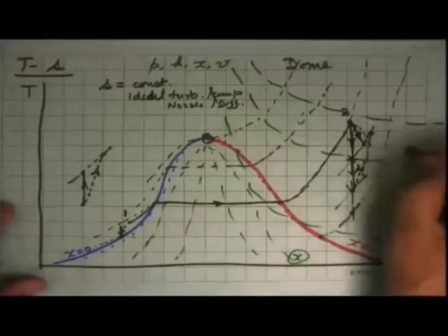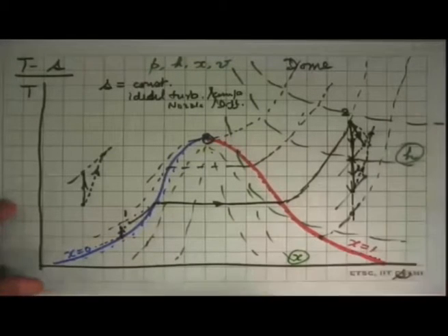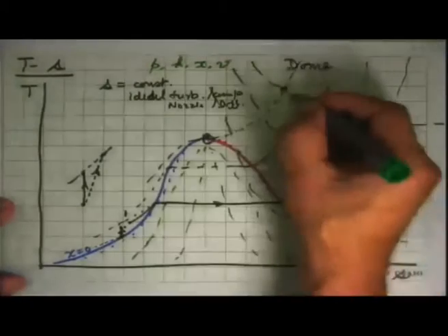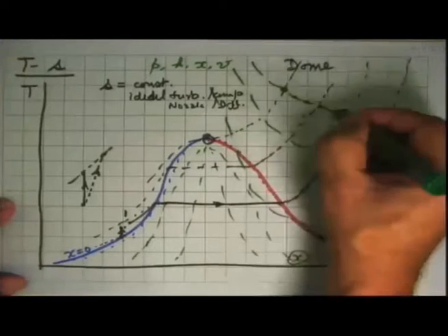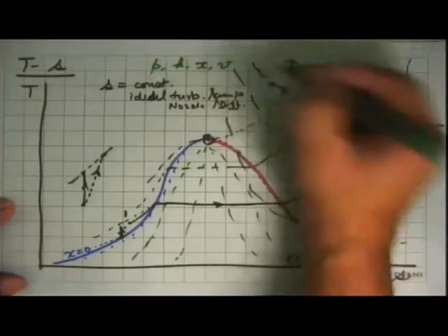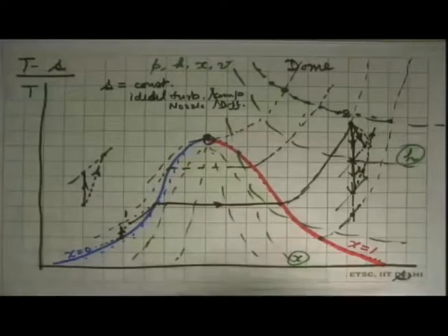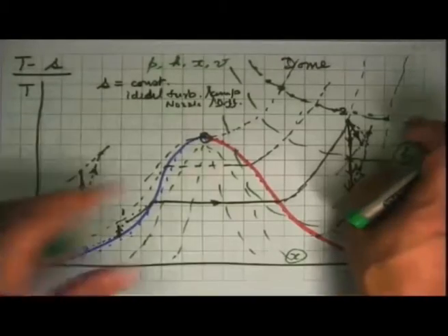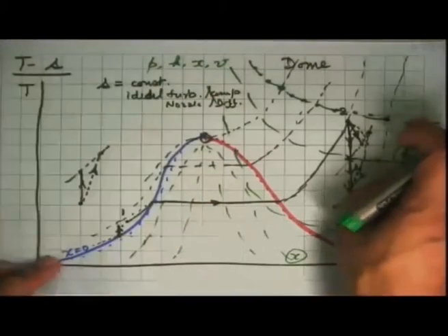So these are constant enthalpy lines. And what it tells you is that if you are going to do throttling from here, that's an isenthalpic process, then the states that one would get will be all along that side and not along this side. Throttling is an irreversible process. Entropy has to increase, so the states will lie to the right and not to the left.